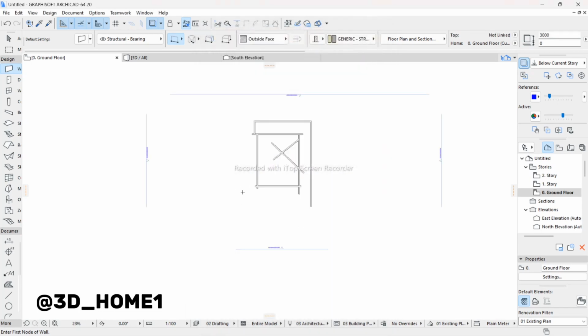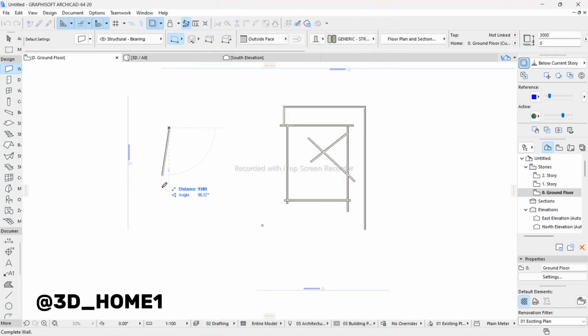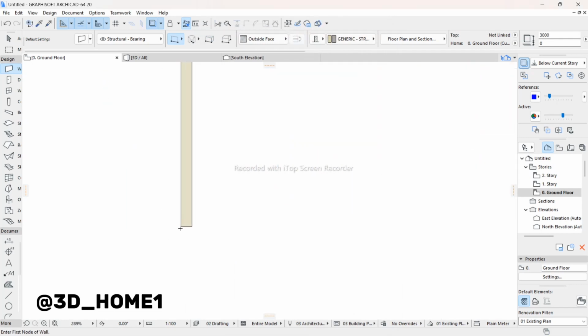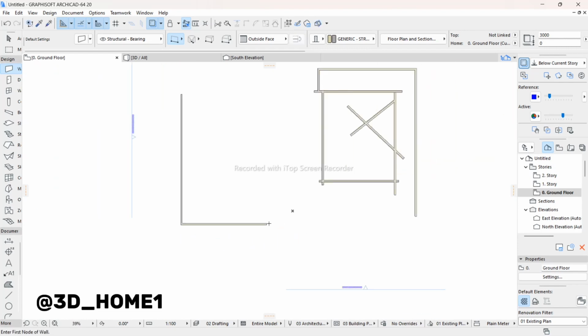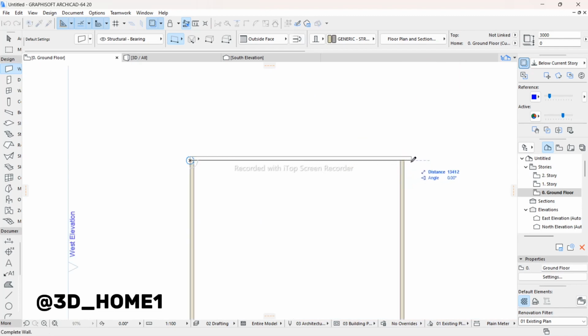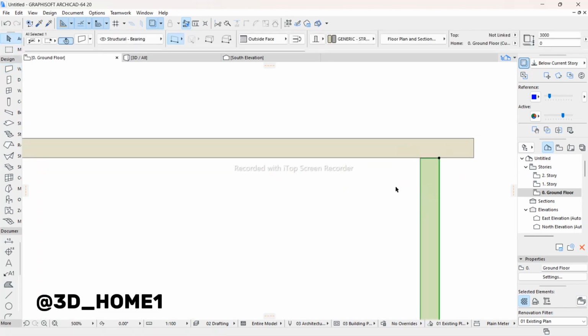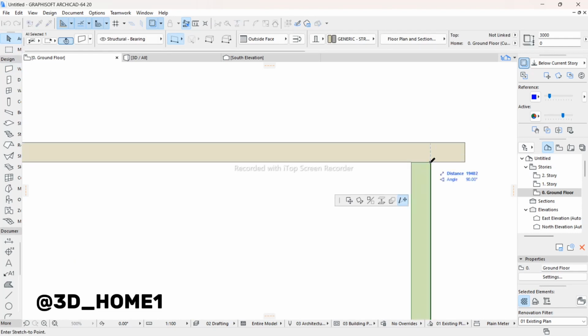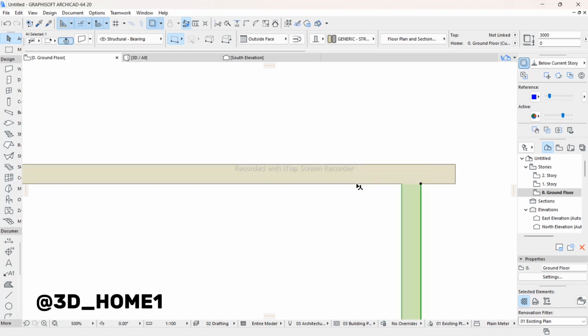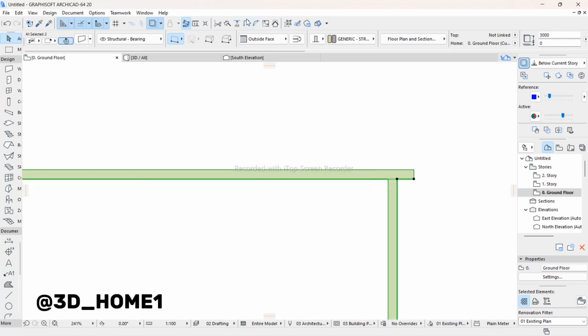Let's click on this, and this is the new wall we're working on now. New wall. Before you draw the second one, make sure there's a circle that shows connection. Click here. I'm drawing on ground floor. This particular wall did not join, so you can drag it from this point, move it inside, press on shift, click on the two walls, then you can trim them.